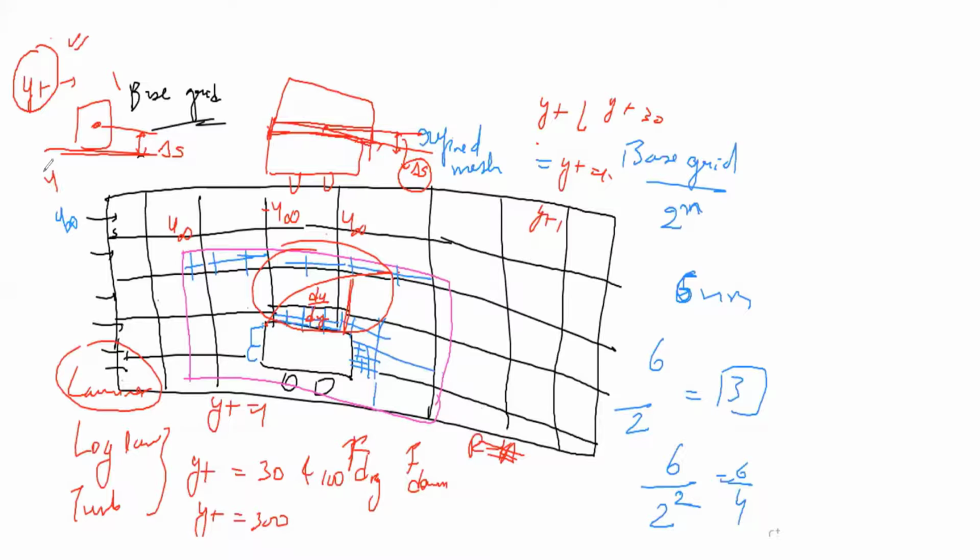And there is an online y plus calculator where you provide the U infinity, Reynolds number value and everything, and it will give you the y plus value. Or if you want to do the reverse calculation, provide y plus and it will give you the other quantity which you want to find. Right? So this is an important thing, guys.